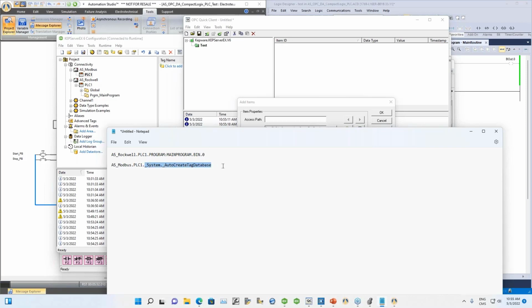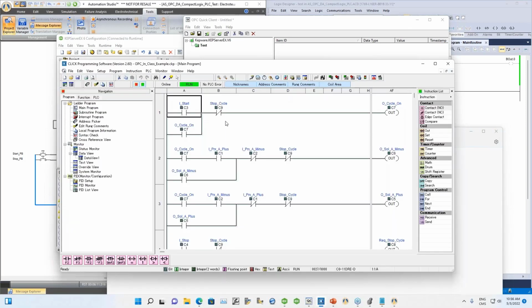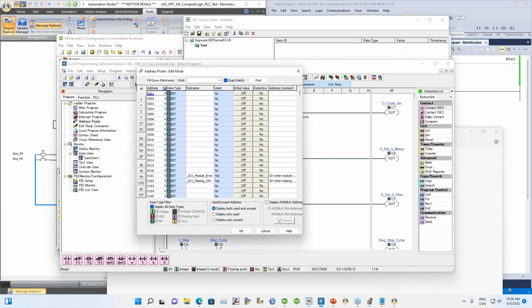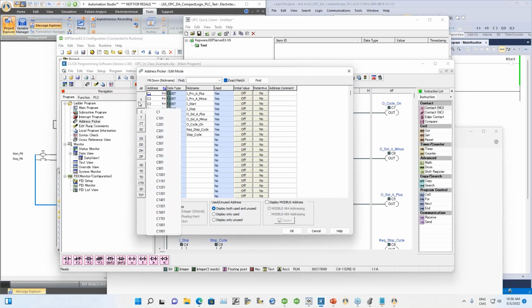I have to take out this part because this is a diagnostic register. And here I have to add the register address inside the Koyo, and the register address inside the Koyo is really a Modbus address. Because it's a different PLC, different technology, different standard, if I open here, these are the registers used inside the Koyo. I'm going to use internal registers, as I said. I never use real card IOs. By the way, I forgot to show you, but I'll show you at the end how to make the link between the internal register and the real PLC address, the real card.